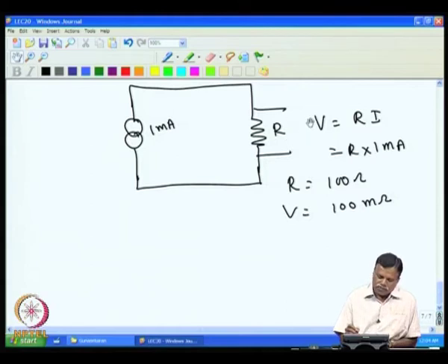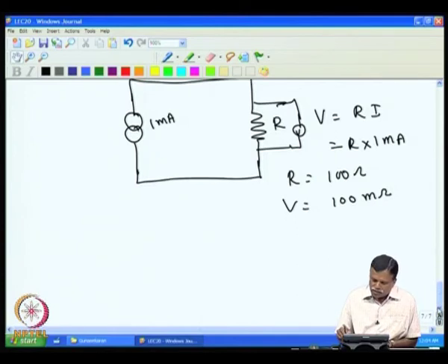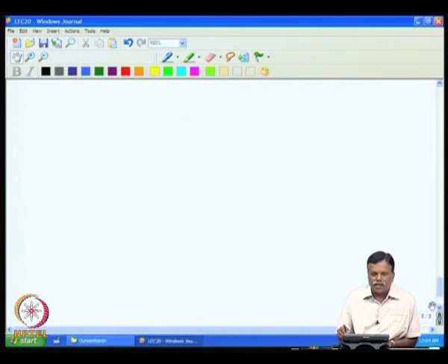And also we will have to put some voltmeter here or some measuring circuit to measure the voltage. This also will drift with temperature. So, the net result is you will have error due to this current change, and error in voltage measurement. This will make the measurement not very accurate.